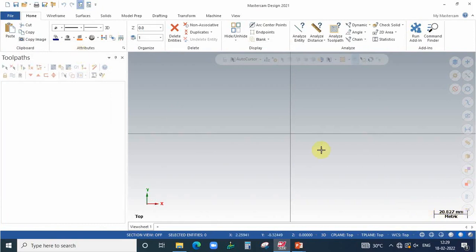The second step is pressing F9. Already the crosshair line is there. Suppose it is not there, you press F9 and we will get a crosshair line like this. We will get 4 quadrants, first, second, third, fourth. Any one of the quadrants we can select for creating the sketch. We can take the middle reference or corner reference, any one. That depends upon the profile.